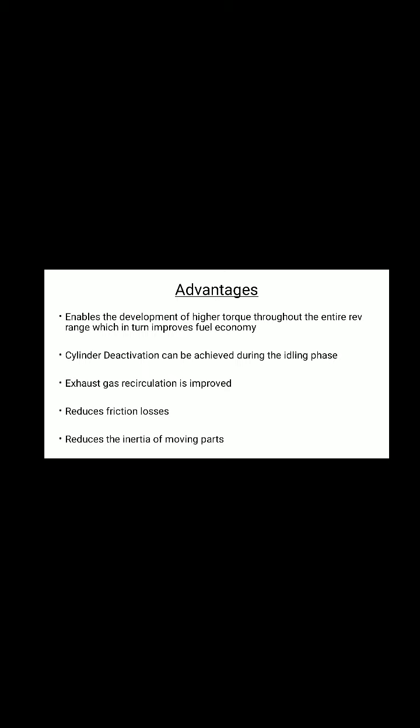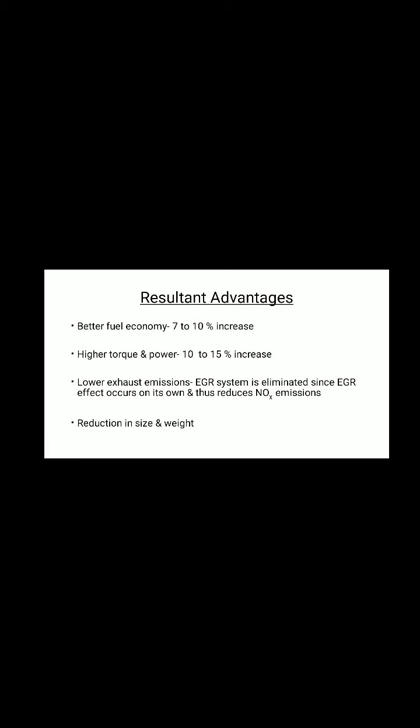Here come the advantages. It enables the development of higher torque throughout the entire rev range, which in turn improves fuel economy. Cylinder deactivation can be achieved during the idling phase. Exhaust gas recirculation is improved, and it reduces friction losses and the inertia of moving parts. The resultant advantages are better fuel economy, a 7 to 10% increase, higher torque and power, a 10 to 15% increase, and lower exhaust emissions. The EGR system is eliminated since the EGR effect occurs on its own, thus reducing NOx emissions, and there is a reduction in size and weight.